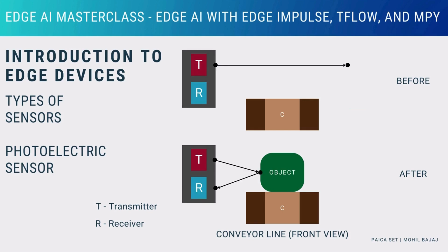The second type are the diffuse sensors, where the transmitter and receiver are housed together, and when an object moves past the sensor, it reflects light back, letting the sensor know that something has passed through. They are the easiest to install, though they may be susceptible to dusty environments, which may reflect light back, and certain object textures, which may not reflect enough light back.